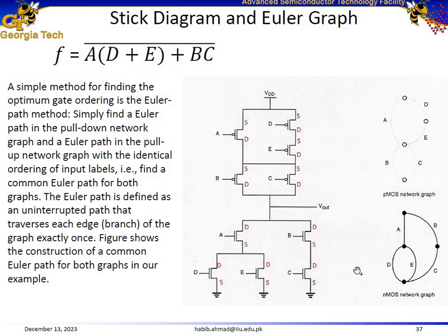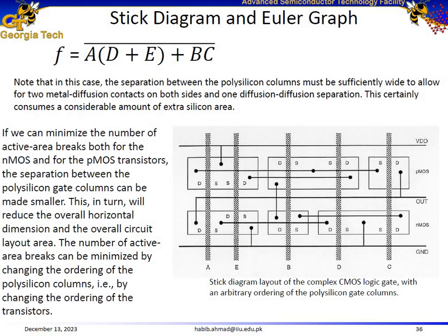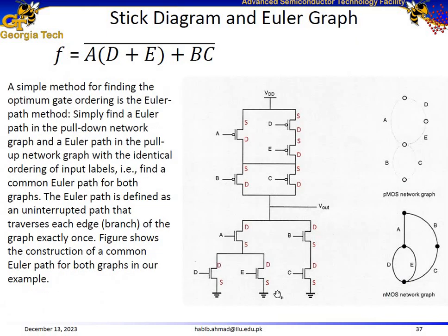Now let us focus on the pull-up network. For the pull-up network, we can start from VDD. In fact, we don't really need to make the full pull-up network by looking at the stick diagram. We can just follow the duality principle.